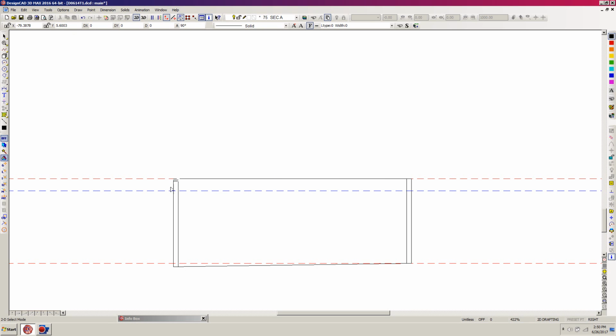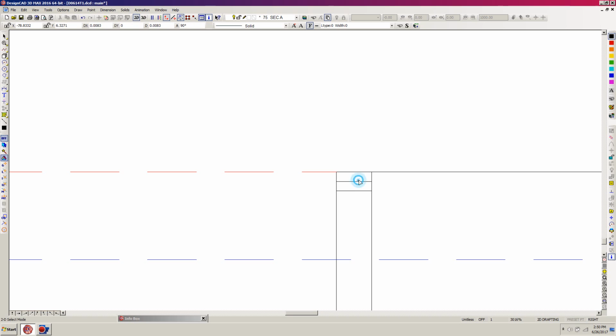Now I want to do the same thing and create a bottom plate down here. So I'm going to cheat, and zoom up on this thing, and select this little plate line here, and click on set selection handles, left click on that, and I want to set my selection handle 1.5 inches below. This lower top plate line is conveniently 1.5 inches below, and I can hit H to get out of orthogonal mode. There's no point in being in that anymore. You can see I'm no longer in that. So I can hit enter, and you can see that my handle has been relocated to that position.